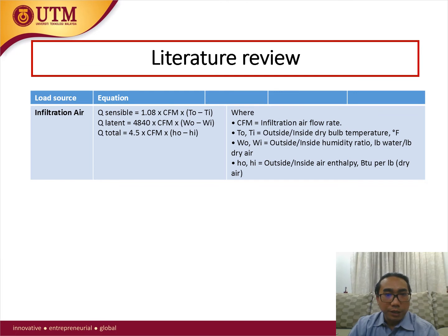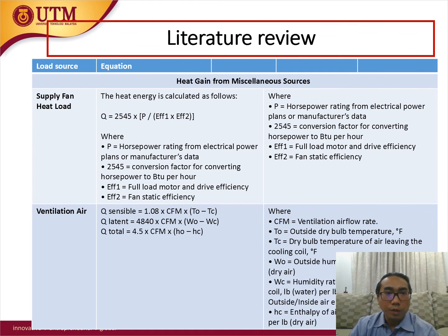Infiltration air, where the airflow rate is calculated, including the sensible and latent heat. For supply fan heat load, supply and/or return fans that circulate or supply air to the space add heat to the space or system, depending on the location relative to the conditioned space. The heat added may take one or all of the following forms.